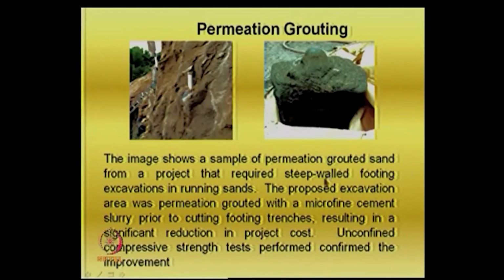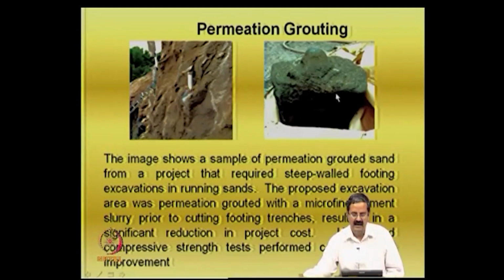And people say, for example, if you test the unconfined compression strength of this material treated with permeation grouting... See, permeation grouting is just a cement slurry except that it has filled up all the voids. So, it can also bind all the particles, and if it can increase the strength in this manner, definitely it is going to be very advantageous, and it leads to a lot of improvement in shear strength and reduction in permeability. All these advantages are inherent in permeation grouting.